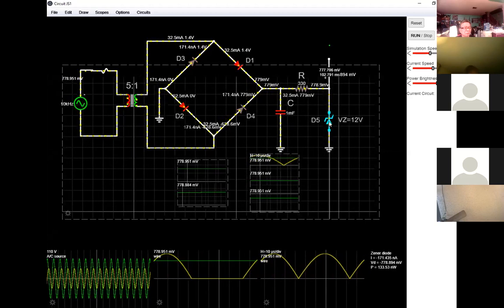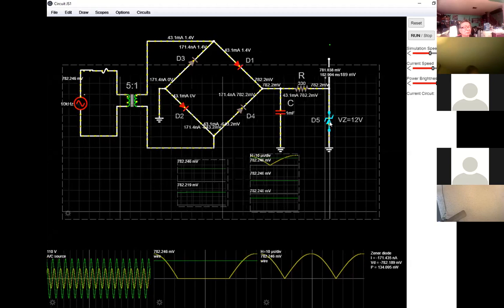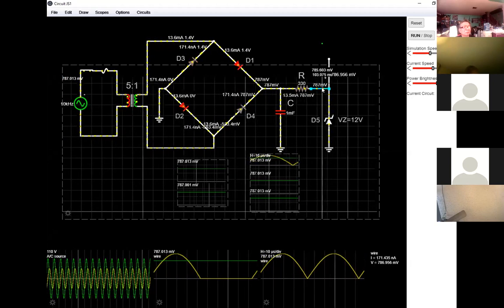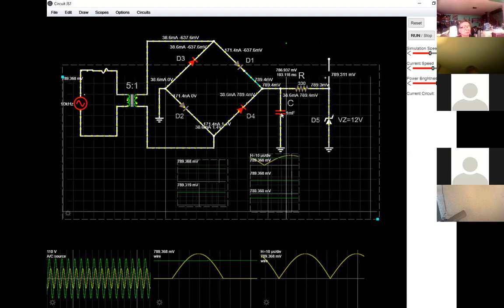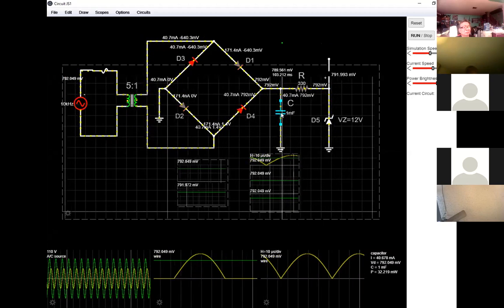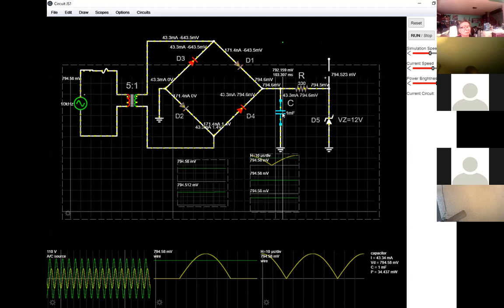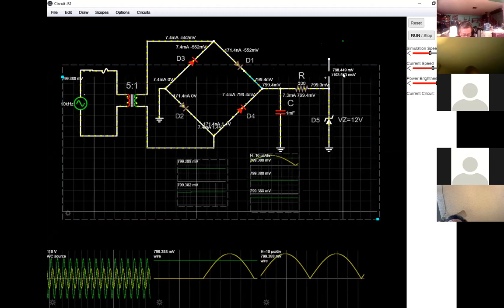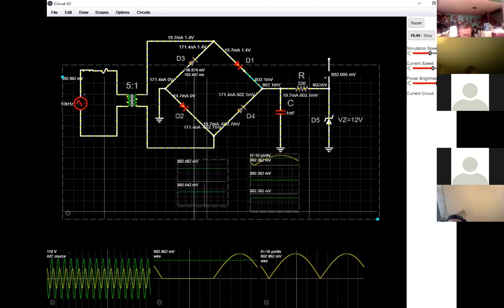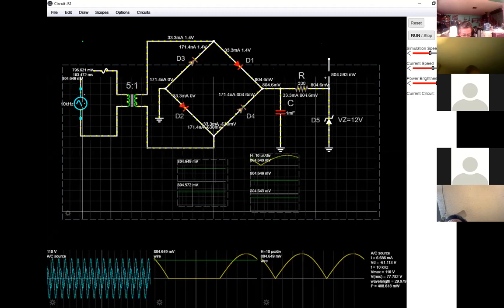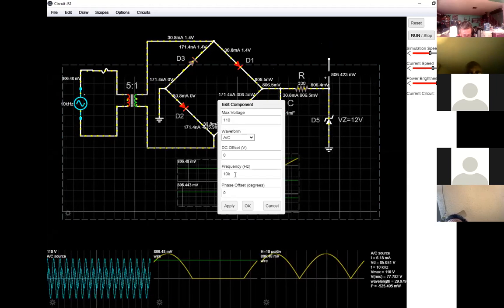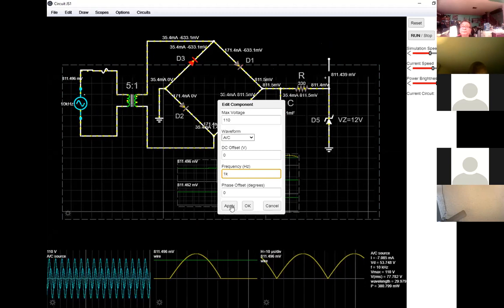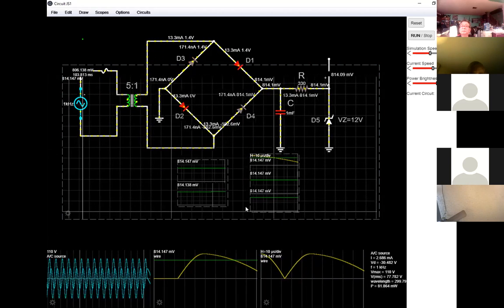Now the only thing that I found that was a complication is the circuit doesn't want to reach up to the voltage that it should be at. And I know I have my capacitor set correctly, but increasing to like the 30 volt range just doesn't happen. So I changed this from 10K down to 1K, just to see what would happen.